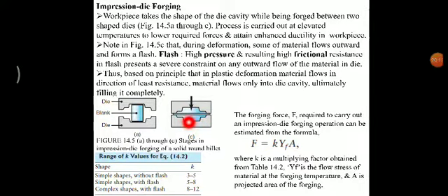It will become difficult when the pressure inside the workpiece in the forced condition or in the last stage is less. But if we have higher pressure or forces experienced in the workpiece itself in this condition, then even miniature sculptured parts, the sculptured design, as you can see in coins also, can be easily filled with metal. So for creating the high pressure over here, we can go for the impression die forging.